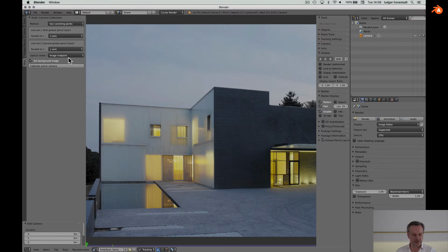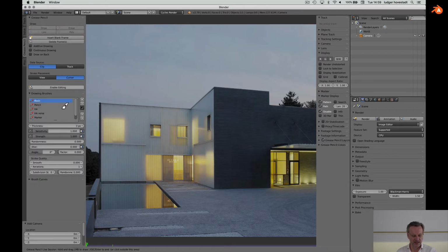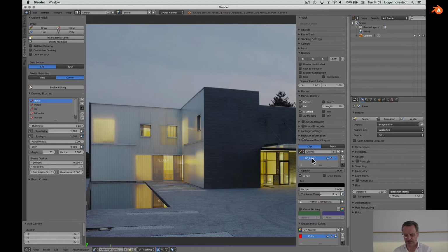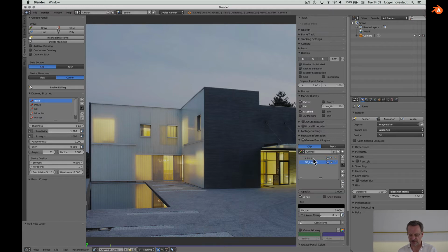So the idea is that you do it with a grease pencil toolkit. This is how to draw. We take a line with a precise, small thickness, so be precise. We give it the color, as is here. Give it red. And we need these layers here. So this is the layer for x-axis. We need another layer for the y-axis. This is what this toolkit needs.